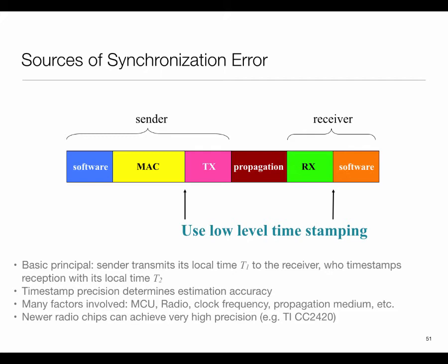So all the RF is doing is generating the signal saying the packet is going out or the packet came in. Then the timer unit of the microprocessor is configured so that whenever that signal comes, you take a capture. No interrupt handling is involved directly in this case.